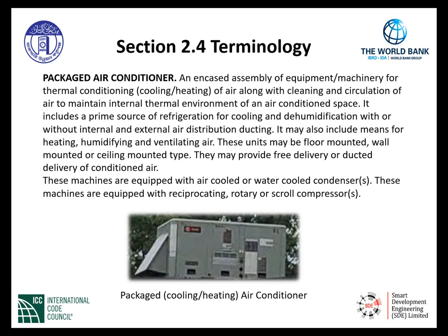Below is a packaged heating and cooling unit that provides all of the heat transfer effects for a conditioned space. It also provides filtration as well, and external ductwork can be connected to this particular packaged heating and cooling air conditioner to have the air distributed to the spaces within the building.